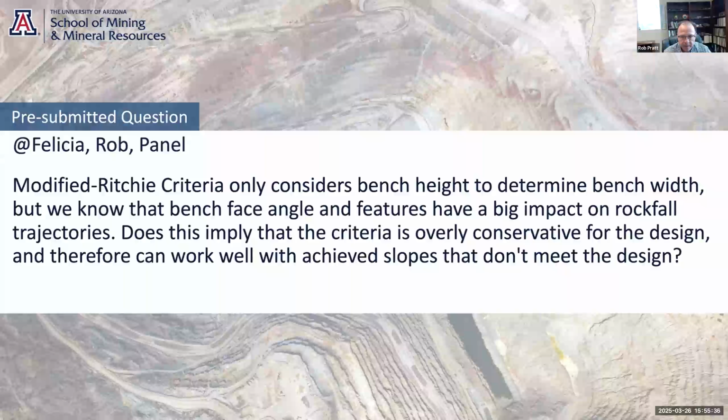But the point is that we can use a certain reliability of achieving this width as a metric towards a reasonable criteria for bench scale design. The nice thing about the reliability component is it allows us to address the issue we talked about just a minute ago in the previous question, about the condition of the ground, how fractured it is and how blast damaged it may be.